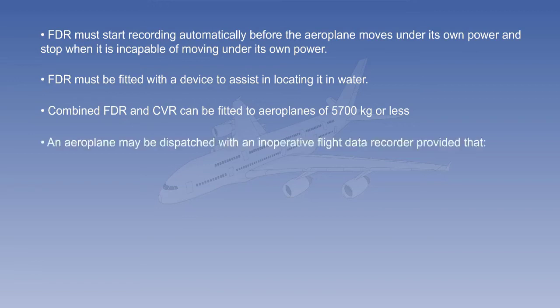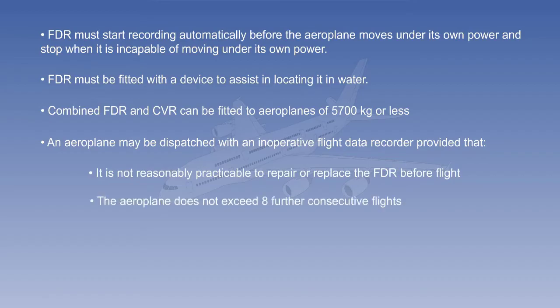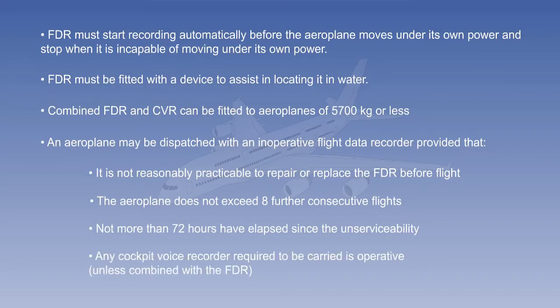An aeroplane may be dispatched with an inoperative flight data recorder, provided that it is not reasonably practical to repair or replace it before the flight. The aeroplane does not exceed 8 further consecutive flights. Not more than 72 hours have elapsed since the unserviceability, and any cockpit voice recorder required to be carried is operative unless it is a combined unit.